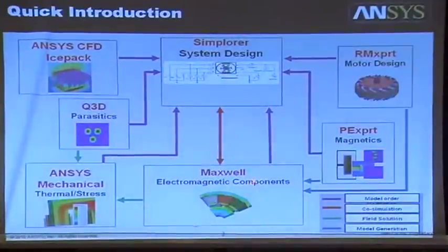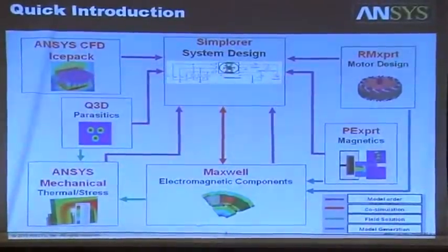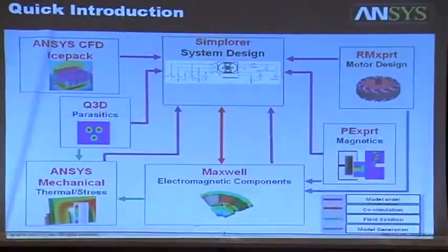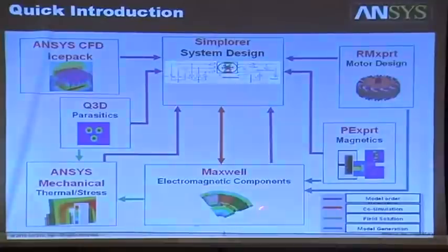Once we take this into the FE domain, we will solve here. We will see the field, we will see the flux linkages, we will monitor the voltage induced. And once we finalize or optimize the design in this, we will be interested in knowing the thermal and stress on that motor.